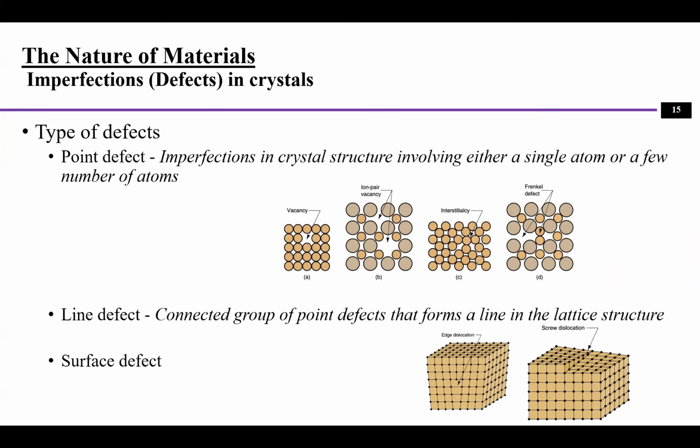Of course, not all crystalline structures have a really perfect pattern that repeats itself. Sometimes you will see some defects. Defects can be a missing atom, or missing a whole line of atoms, right? Or sometimes you will see a whole surface of atoms missing, and these are called point defect, line defect, and also surface defect. And having all these defects will certainly affect its mechanical properties.